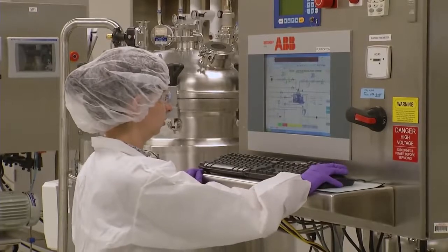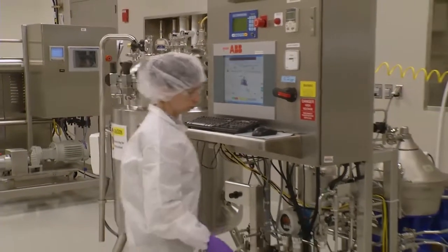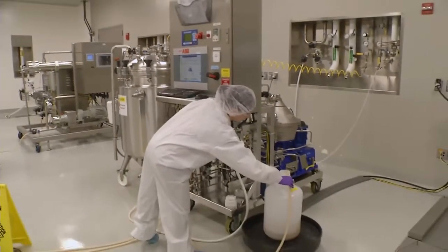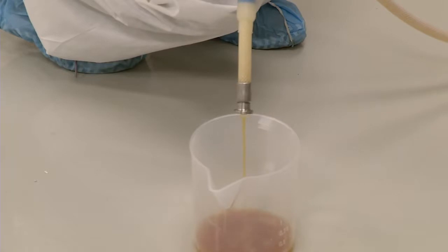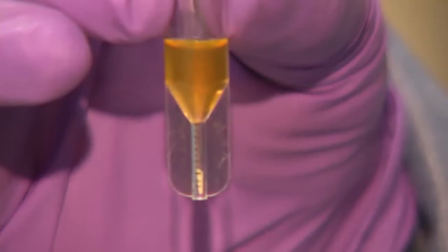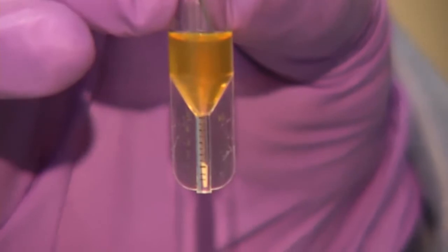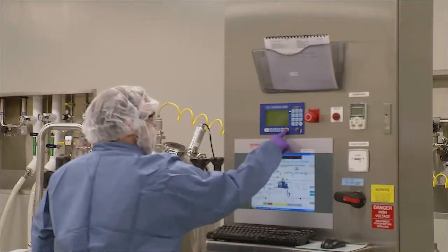The centrifuge has an integrated RPM monitor. If the unit is not rotating at a stable running speed, the controller will alarm and shut it down. The liquid leaving the bowl is known as the clarified stream because almost all the solids have been removed. A sensor monitors the clarified stream for percent solids. When this value rises, it indicates that the bowl is at capacity and the solids must be removed before processing